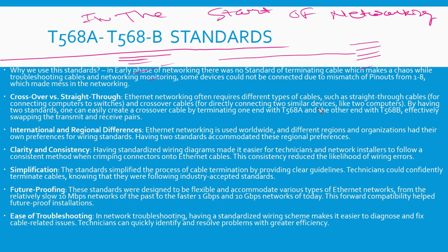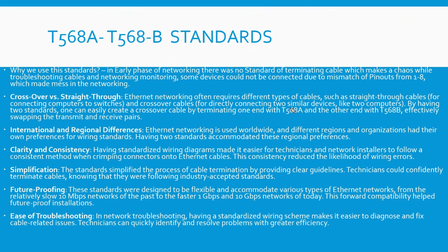You will never be able to understand how to terminate the other side of the cable because you never know which side is which. You have to use a toner and a lot of testers to test the cable, and then you identify the cable. Then you have to check on the other side, and then check on the other side again. So we made a standard, at least to keep it the same way, to clear the confusion and clear your doubts. Everybody will terminate either A or B, so you can easily troubleshoot the network.